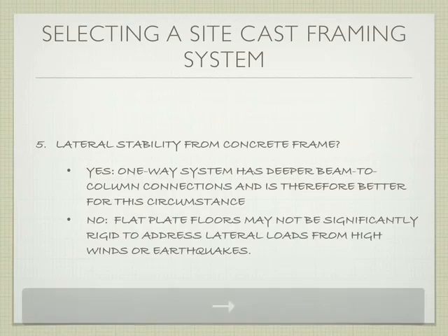And so the last thing is, are you in some kind of an area or a zone that's subject to a lot of earthquakes, and those types of conditions? If you're in an area that's subject to that, you have to pay a lot of attention to how you're going to connect the column to the slab, and how much concrete and how much reinforcing it's going to take to make that a stable system for an earthquake environment.